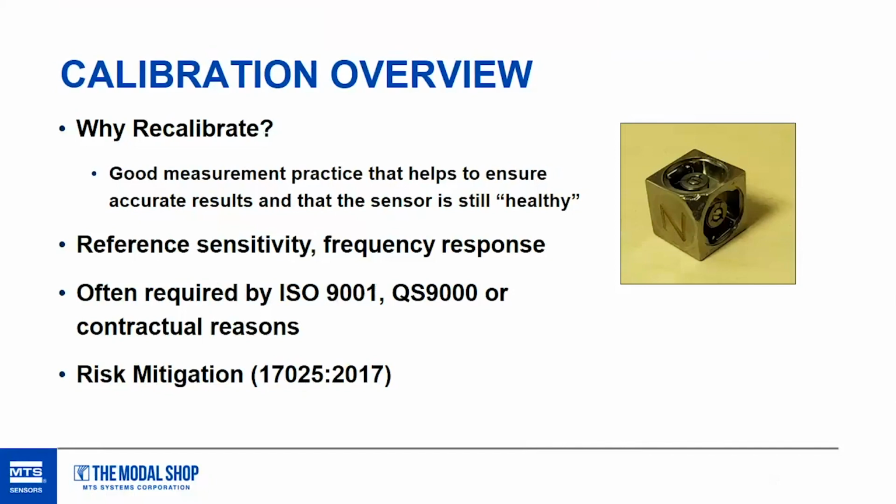It's going to change the frequency response characteristics of that sensor. So yeah, Joe, careful with the screwdriver. It's going to affect the results of the sensor over time. So take care of the accelerometer and you'll have consistent data there.